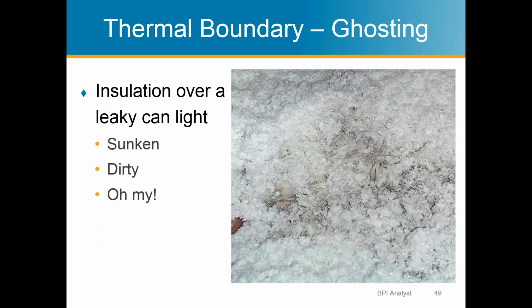You could use the same insulation, and it's going to be a lot better. Ghosting, it's a less obvious picture of ghosting, but anytime there's any discoloration in the insulation, that's just showing the air has been moving through it. Insulation's a great air filter. And that's basically what it's doing, is filtering the air for you.